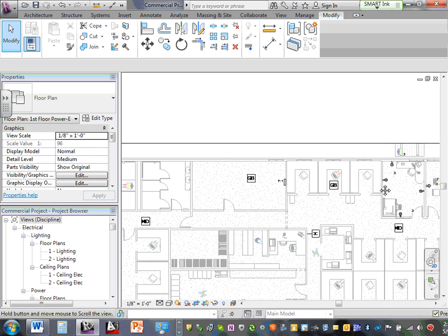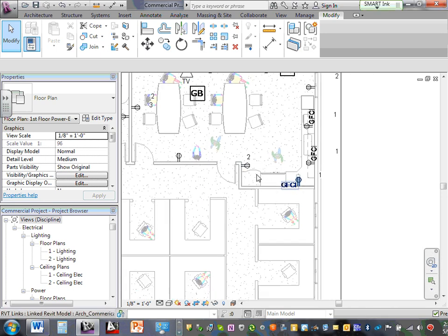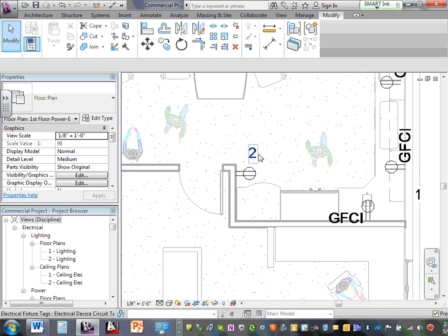Now, when you have multiple, let's zoom into that circuit breaker, any of the circuits. Now, when you have 5 panels, how can you tell that this receptacle is coming from which panel? Can you tell by having just number 2? No. Now we're going to edit the label of the receptacle to indicate 2 things, the panel and the circuit. We do this all the time, guys.